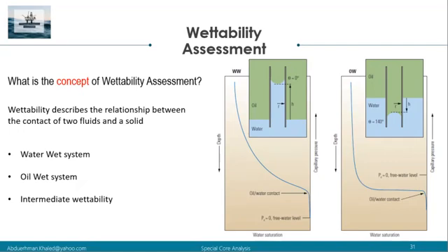Sometimes because of the lithology variations, we have different wetting states. For example, the tight zone may remain water wet if the oil could not migrate to that space. I mean, they are basically water wet, and they became water wet because the oil could not reach that pore space. Okay, because it required a high capillary pressure, and that pressure was not available for the non-wetting phase, while the surrounding formation was converted to a more oil wet state.